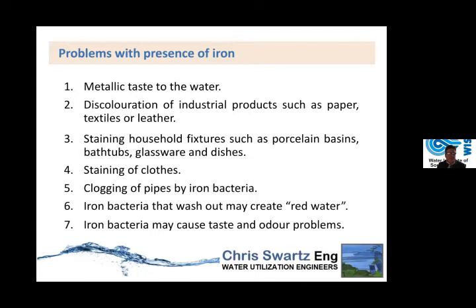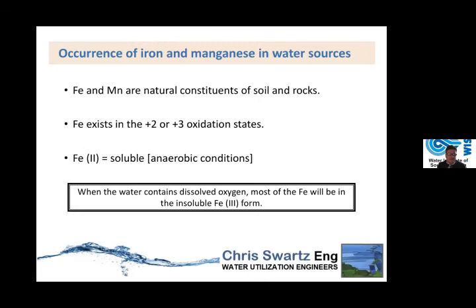So the problems with iron are metallic taste, discoloration of some of your household and industrial products, staining of clothes, and clogging of pipes with iron bacteria. Of course, iron bacteria like this water very much, and then it creates red water if you wash out this iron bacteria. So a lot of staining, aesthetical problems mostly, but also aesthetical in terms of taste, metal taste.